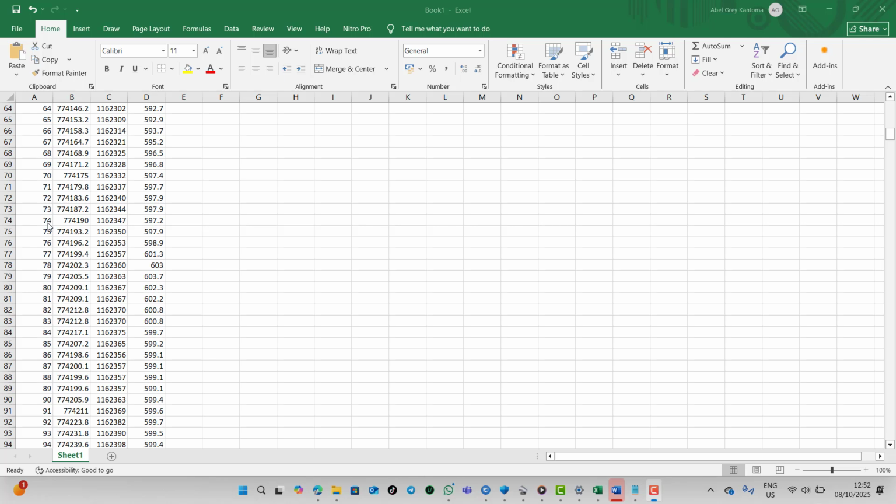So if you look at this now, like I said earlier, this is our point, this is our easting, this is our northing, this is our elevation. Similarly, if this was to be here and this easting value to be here, it will now be point, northing, easting, and then elevation. Right, so by the time we open our Civil 3D software, I'll be able to explain that better in order for you to understand. I have spoken extensively on this. I wouldn't want to go too far anymore.